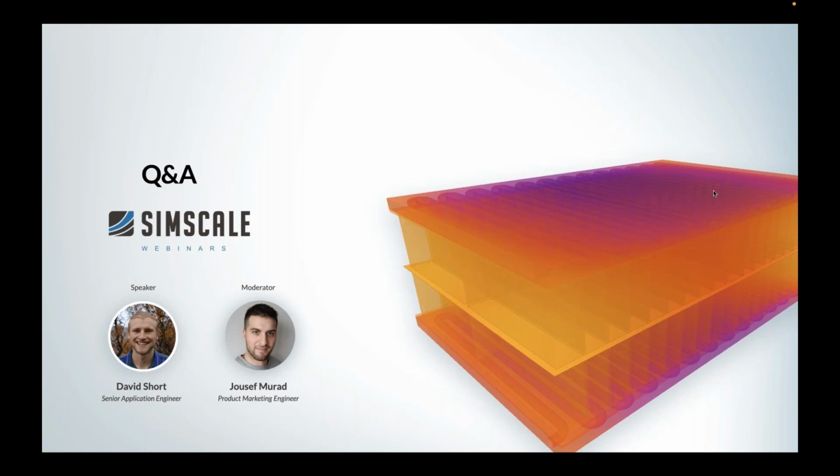Great, I think that covers it. And the last question we have coming in is if real-world data can be considered in our simulation, so basically imported into the SimScale platform and then setting up a simulation. There's obviously the material data, for example, that needs to be influenced by experimental data. So if you're using a nonlinear material, so you've got a nonlinear stress-strain curve, that will have to have been produced from experimental data. We've got a lot of defaults that come from that experimental data as well, but there's a lot of ways we can implement experimental data.